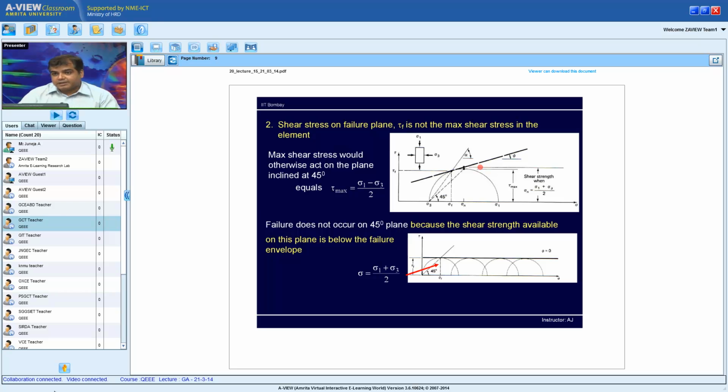So when it coincides with the failure plane, in this case, this point should pass through the topmost point. It can only pass through the topmost point if this envelope is horizontal. Now this horizontal envelope, or the 45 degree plane, you can do a test under this scenario, meaning the test conditions will dictate how this envelope can be formed, and like I said, it will be a part of your further shear strength study.